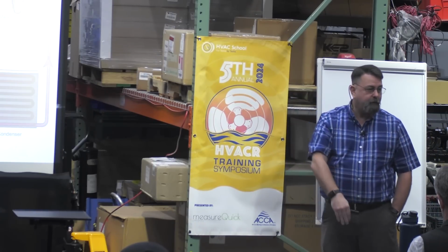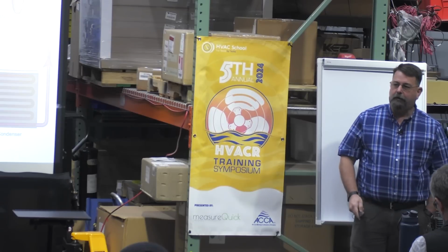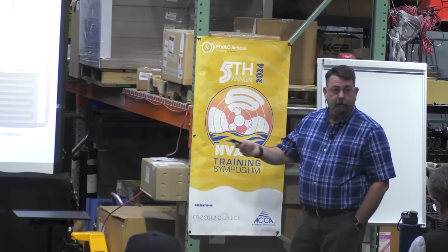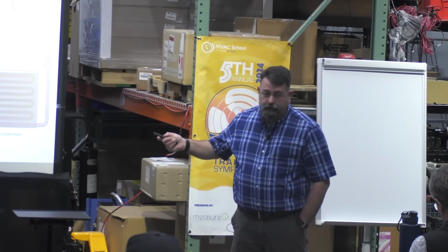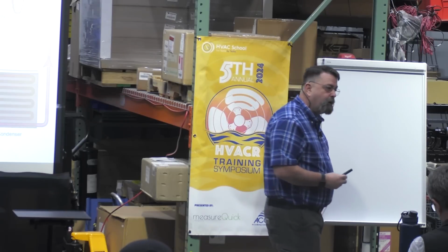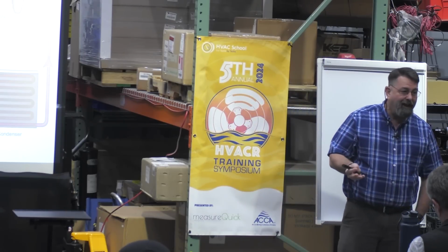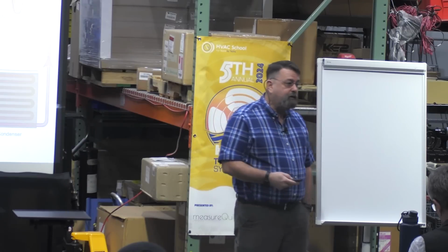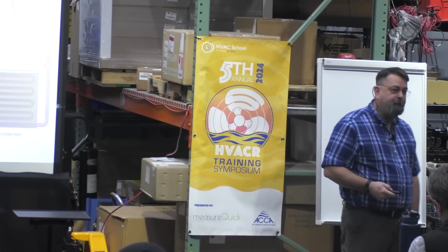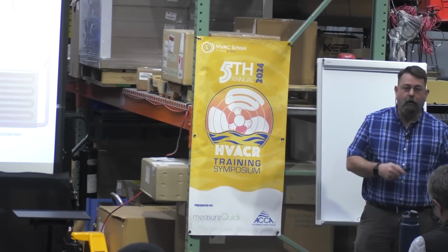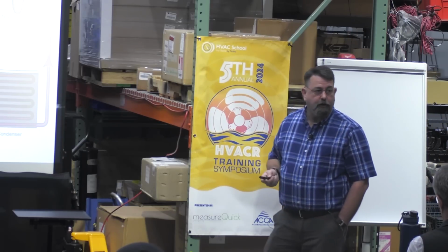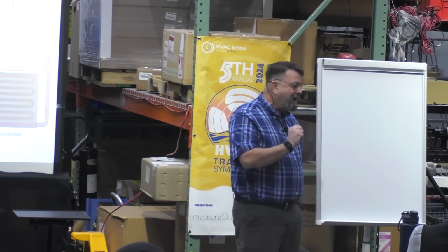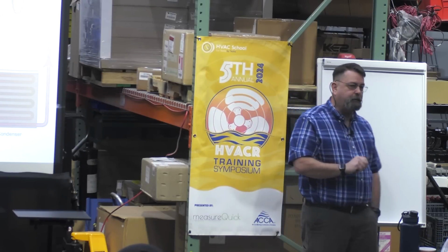Will that not cause my suction to fall? Of course, right? So I'm going to stage my compressors based on my suction pressure. That's what's going to control whether I need more compressors or less. If I'm trying to control 40 and I'm down to 30, I'll turn off one of those compressors on the rack. I'll stage down. I'll have a smaller compressor. That'll cause my suction pressure to go up, right? So I'm going to maintain a very precise suction pressure.